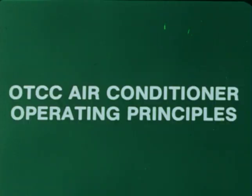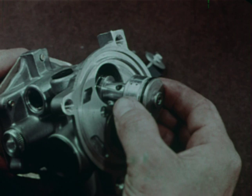Now that you have an understanding of the controls, let's look at the operation of the system. The OTCC air conditioner functions on the same basic principles as the POA and VIR systems you are accustomed to working on. However, there are 2 major differences in the OTCC as compared to the other systems. First, let's consider the method of metering liquid refrigerant into the evaporator.